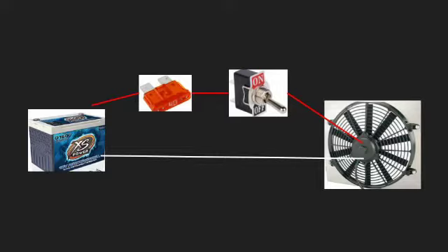And that's the resistance from the time the current leaves the battery and travels to my fuse, if it's a fuse circuit, from my fuse to my switch, through my switch, from my switch through the wire to the fan motor, through the windings of the fan motor, to my chassis ground, if it's a chassis grounded component, through my chassis, the metal of my chassis, from my chassis ground, or from my battery ground, I should say, through the cable up into the battery and back to the return to the source.